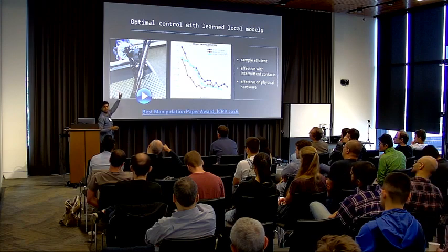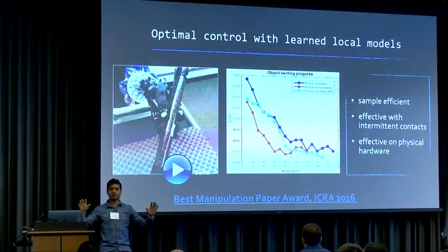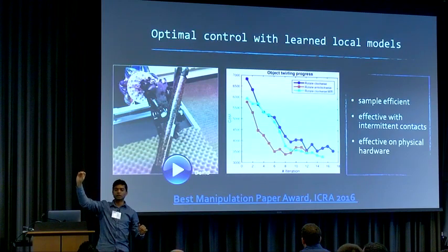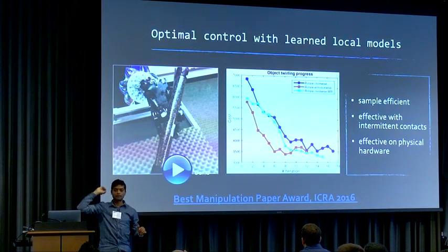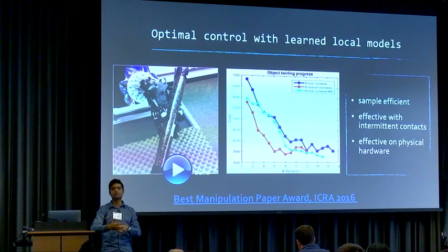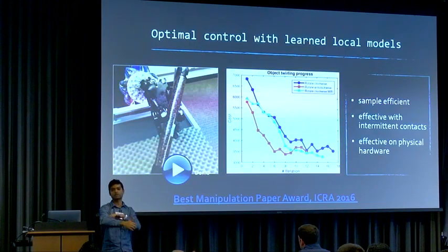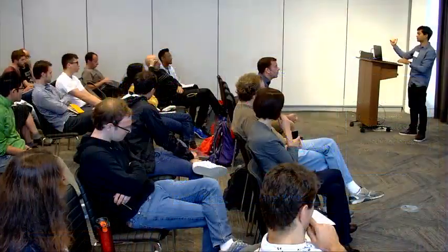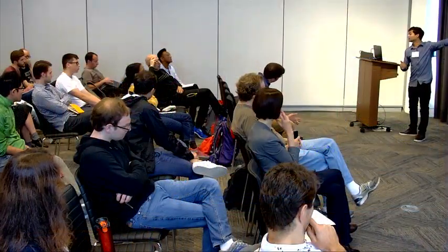We don't even have a model for pneumatics. We are directly controlling the voltage at the valve. And what's the size of the state dimensionality? 112. We have all the joint angles, joint velocities, the pneumatic pressure, because that's a third order system, so you've got to add that pressure into the system, the first order derivatives of that, and information about the object.